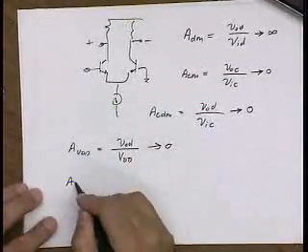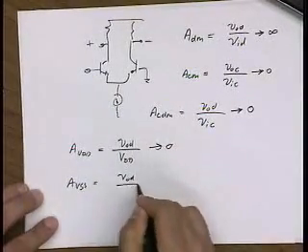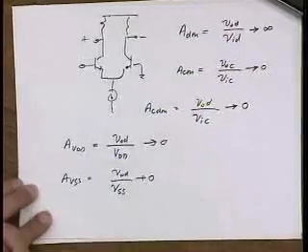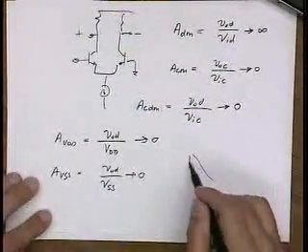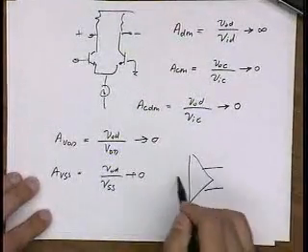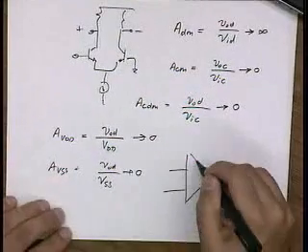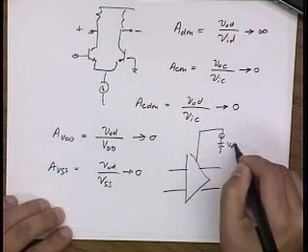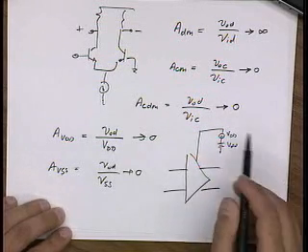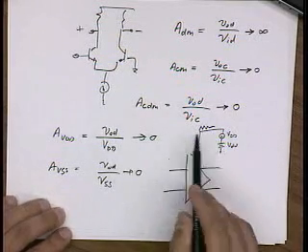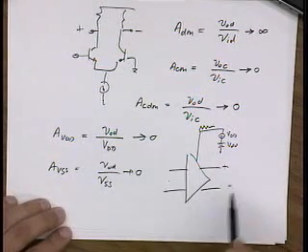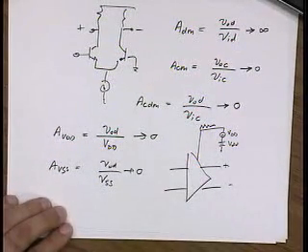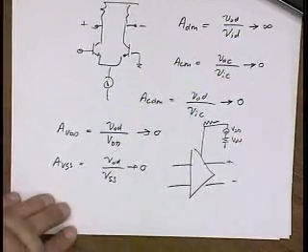And of course, the same with ground. So what am I talking about? Well, I have an amplifier, fully differential, and I put a small signal on VDD. So this is the noise on VDD. I don't want it to generate a differential signal. If it does, it's a really bad differential circuit. Okay?